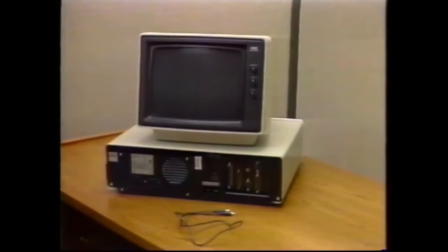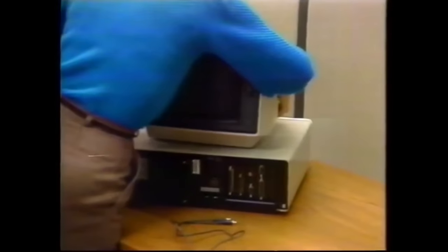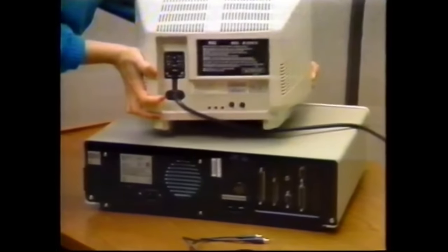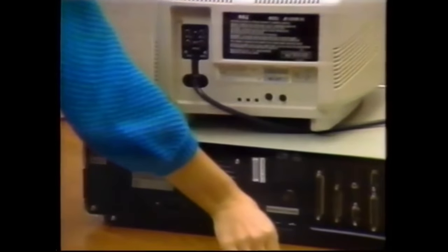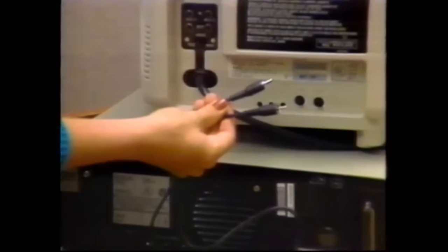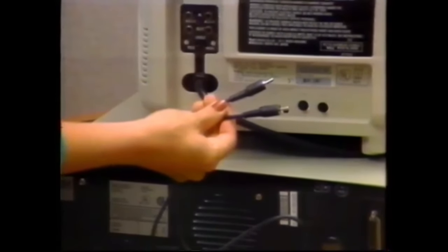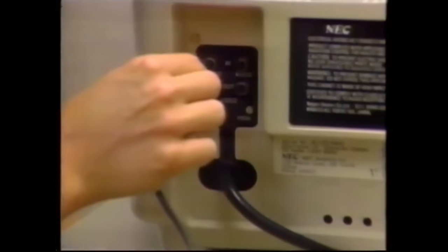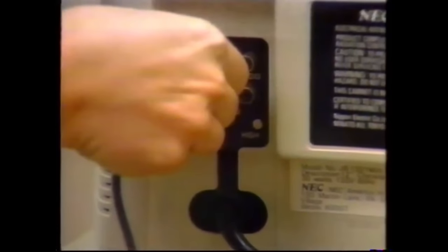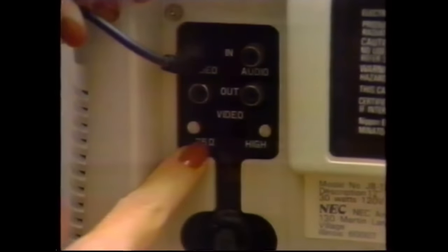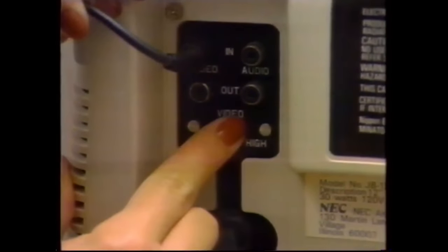If you're not using an IBM monochrome display, you can use another manufacturer's black and white or green screen video monitor. If this is the case, find the cable that has phono connectors on both ends. It'll look just like those cables used on videocassette or stereo equipment as we show here. Plug one end of the phono cable into the phono jack on the back of your monitor. If there is a switch labeled 75 ohms or terminate, be sure to switch to the 75 ohm or terminate position.